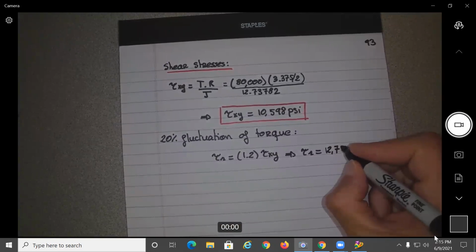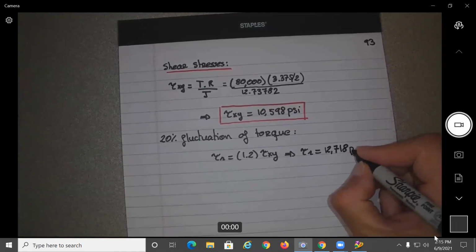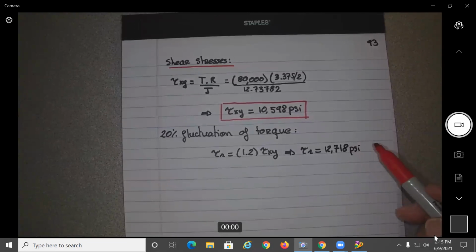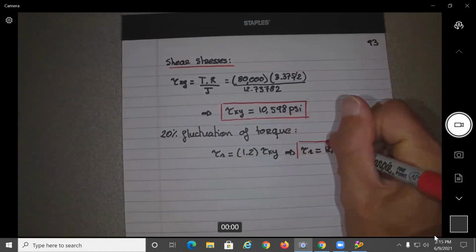So 17, 18, okay. So we keep it simple. The same thing that is important to be accurate for the moment equations, not to round off, because that can create issues for the deflection curve. For stresses, go ahead and always round off high, no? Okay, it's not gonna hurt anything, okay? So you need to be careful. So really this will be 20% higher.